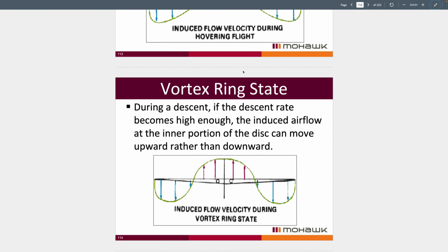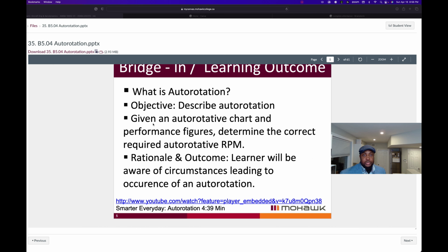So what is autorotation? Autorotation is the method in which a helicopter is able to sustain flight after engine power is lost. In colloquial terms, it's a controlled fall in which we utilize the main rotor's existing RPM to be able to produce enough lift to give a pilot a successful attempt at bringing the helicopter down to the ground.